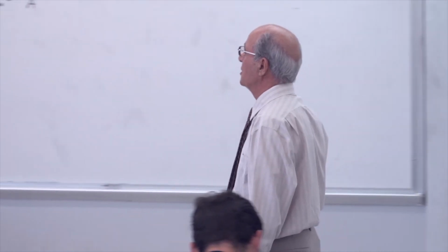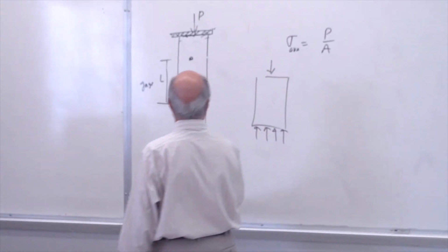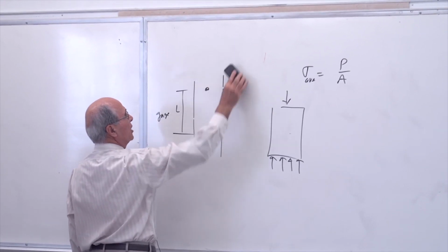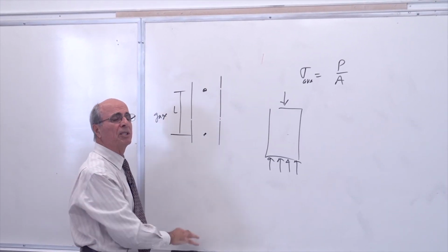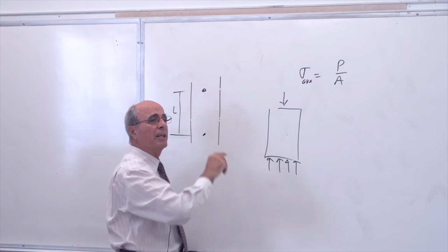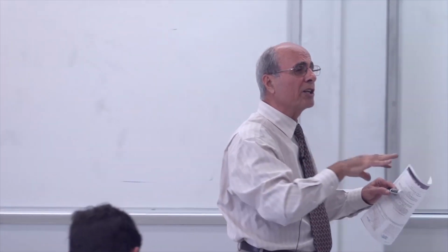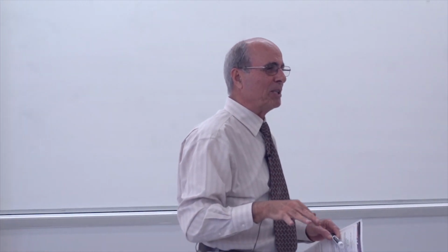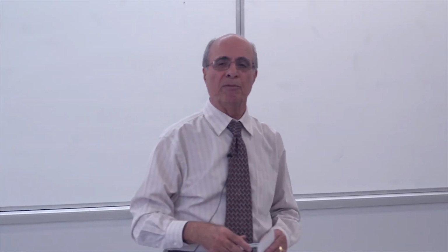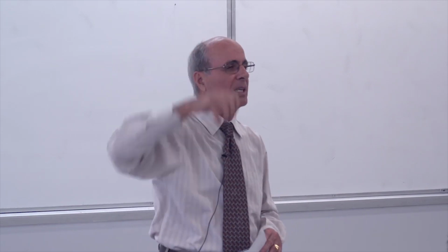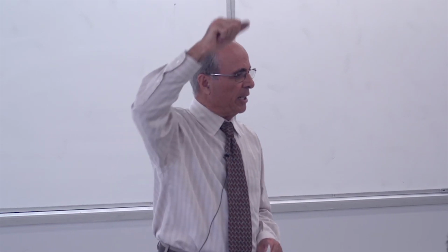It's not important. It's not part of our analysis. You have to be aware there is a stress concentration here, a stress concentration here, so you should be able to remember some of your homework, they put 2 dots here and ask you to calculate the stresses between those 2 dots. Those 2 dots are the gauge length. Everybody calls it gauge length. That's for your information. Some people ask me, so what is this gauge length? That's the gauge length, getting away from the connection area there.